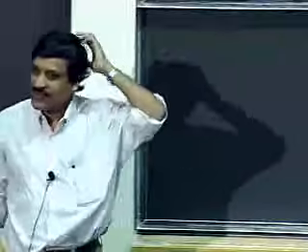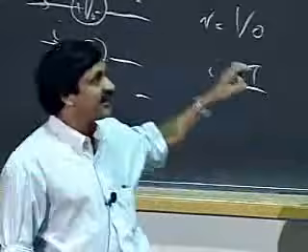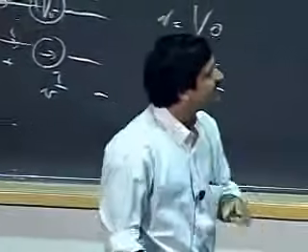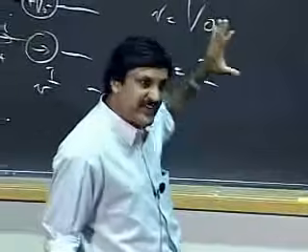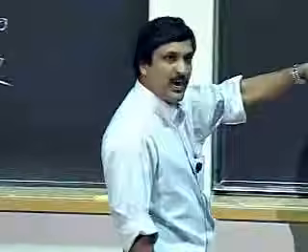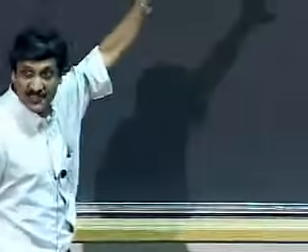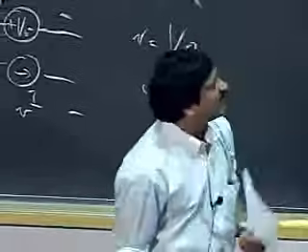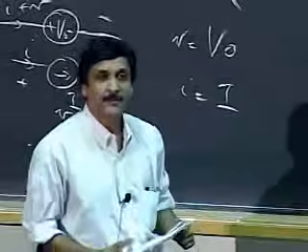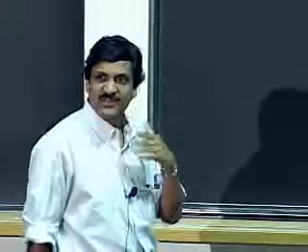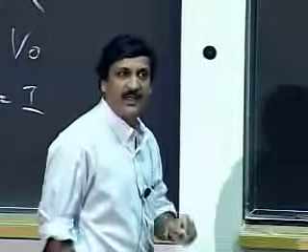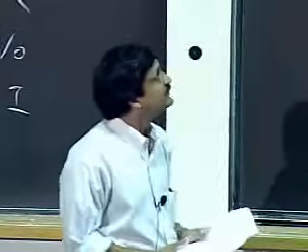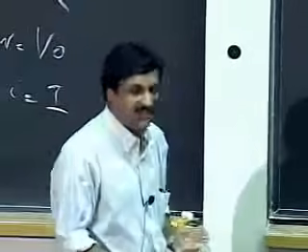However, notice that this is quite a grubby method. It's quite grungy. I get 12 equations, and it's quite a pain, even for a simple circuit like this. However, suffice it to say that this fundamental method that is just one step away from Maxwell's equations simply works. So what we'll do in the rest of this lecture is introduce you to a couple more methods. One is an intuitive method, and another one called the node method is a little bit more formal, but is much more terse than the KVL KCL method.